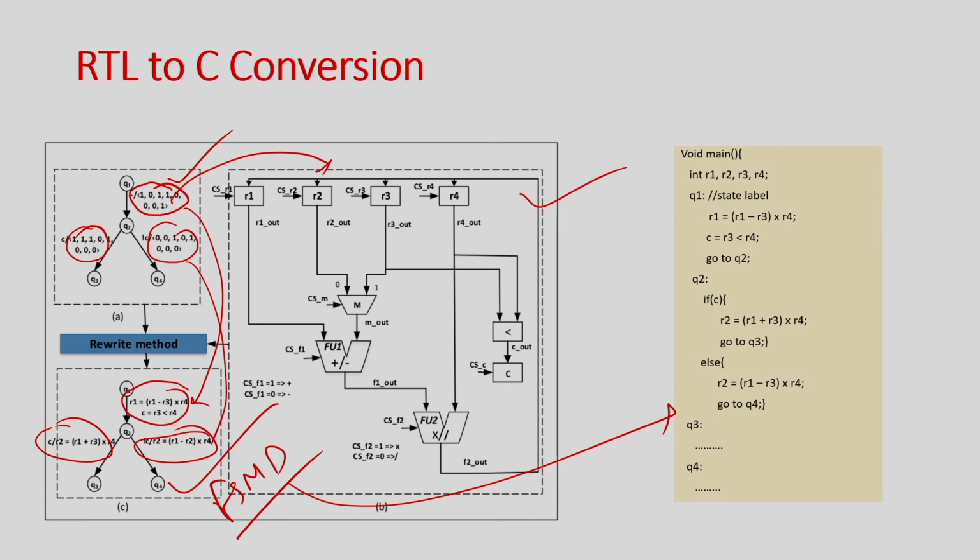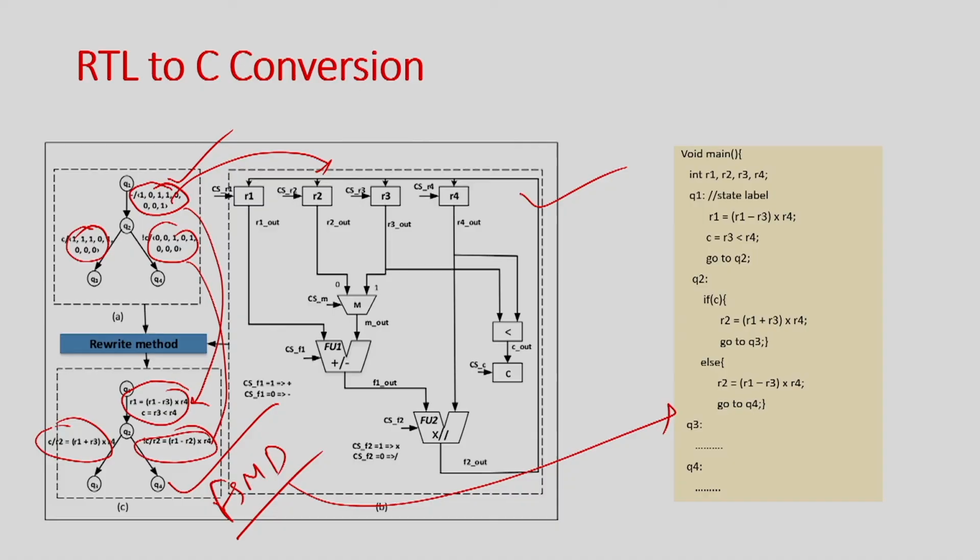Okay. So, the approach that we are going to take is that we convert this RTL into an FSMD by the RTL to C conversion method that we have already discussed, and now we have two behaviors which are comparable. Now, I am going to check what could be the equivalence checking method here, and what the problems are. Although we have two FSMDs, is it the same problem that we have solved for scheduling verification, allocation binding verification and so on, or is it something different, right. So, let us try to understand that.